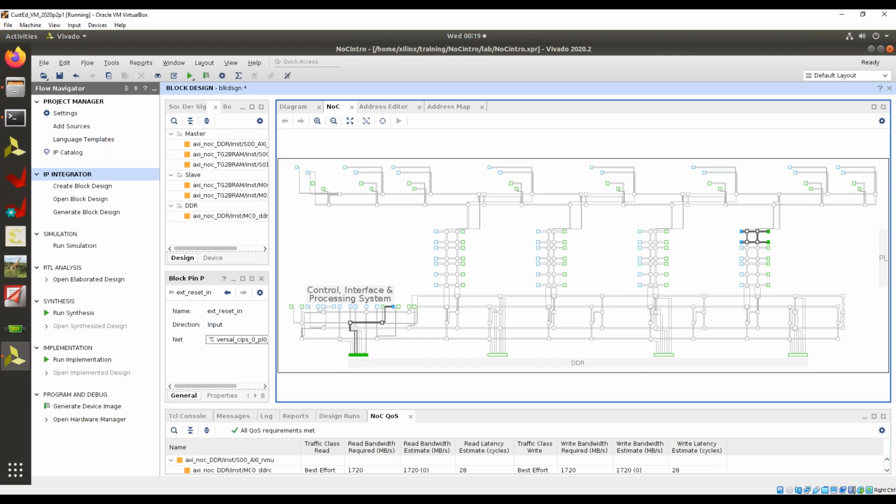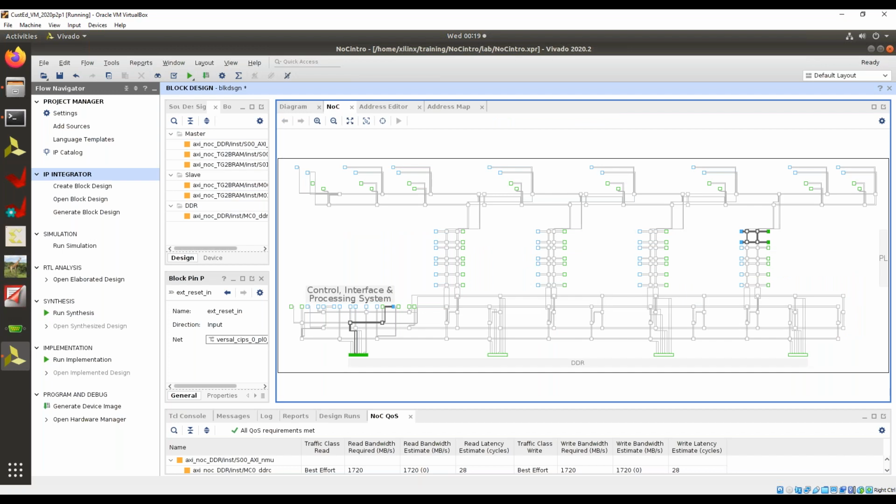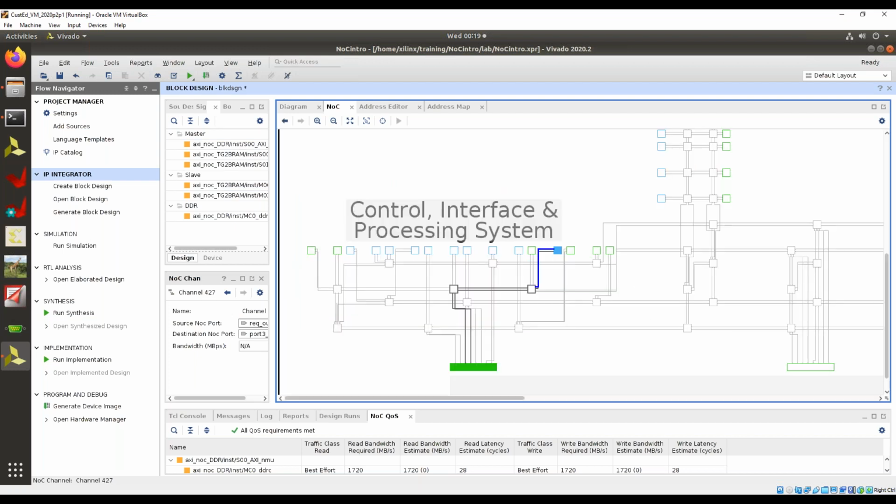We go in and we look at it and go, oh, okay, well, this is what we expected from our diagram. There's our SIPs block that's talking through the NoC to our DDR4, and then our traffic generators that go down and talk to our block RAM. So they're all evidently here. And what's nice is you've got that color coding again, where you've got blue in this case highlighted deep in blue, and that's the path that it actually uses to get down there. So you can even click on it and you can see all the different paths that are available to it.